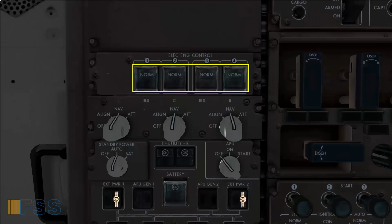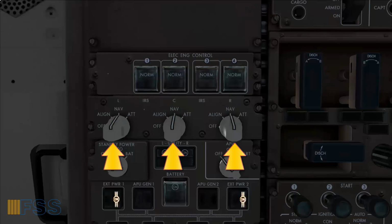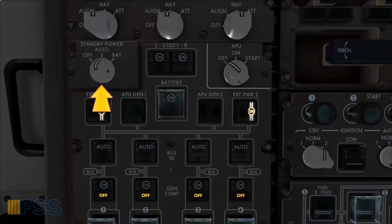EEC switches normal, IRS selectors on nav, standby power selector auto, left and right utility switches on, APU leave it to off for now, it will be started just before engine start.